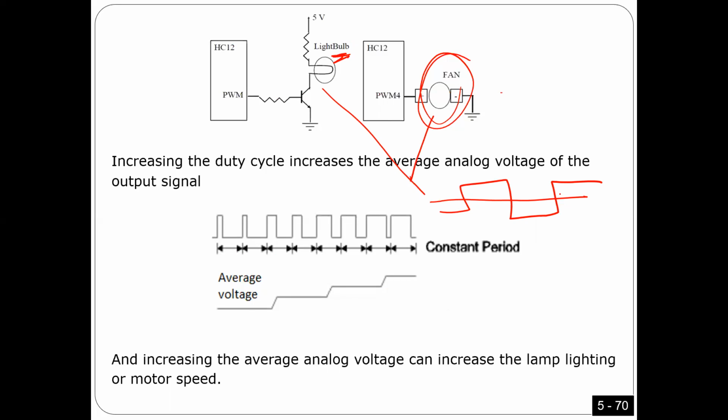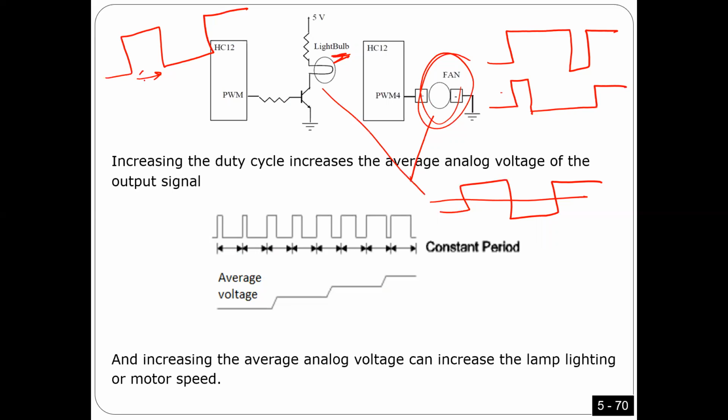As we increase the duty cycle, the average voltage should increase. So for example, this one has a much bigger average voltage than this one. Remember what the duty cycle is? The duty cycle was T on divided by T, times 100 to be a percentage. So how big the duty cycle is tells you how big the high voltage is here.